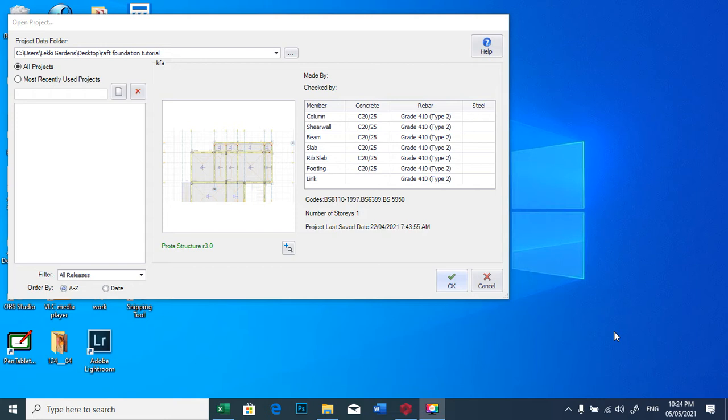Basically two things. One, if your soil capacity is not too good for it to be carried on pad foundation, then you can introduce raft foundation. Or if you have very high loads coming on the foundation, maybe you are doing a high-rise building, so you will need a raft foundation to take care of it. Two things, that is it.